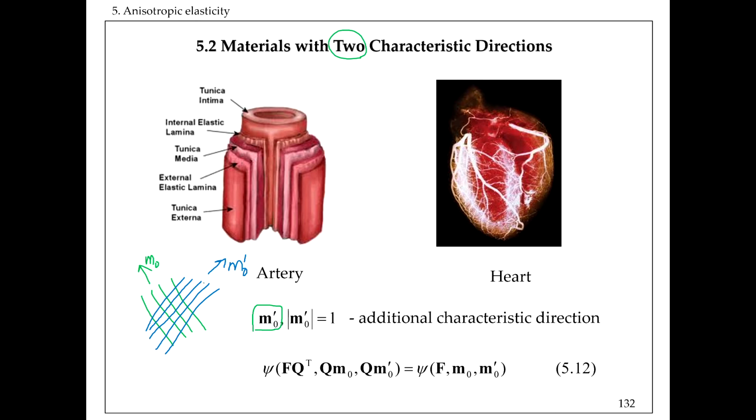Again, it is quite popular in engineering materials to put some fibers in one direction in one layer, then have another layer with other fibers aligned in the other direction. We can repeat these layers, and overall we can have some homogenized response of that material that will have quite good strength against tensile loadings in the direction of the fibers, and when applied in this direction and in this direction, and they also contribute somewhat to the other direction.